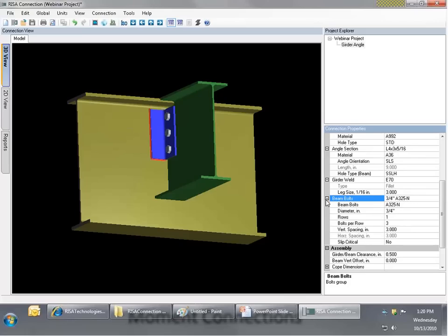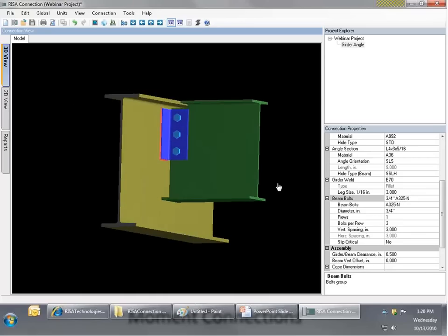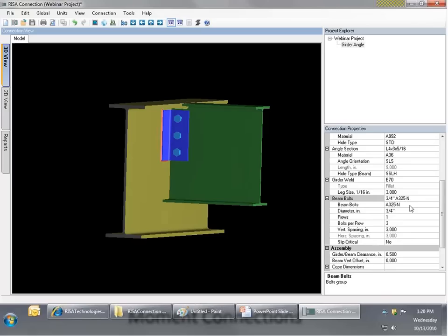And that's what's been set up here, but if I expand this out, you could see I could actually come in and I could set this in any number of different ways. For now though, let's say that I did have these beams with this 45 kip load. I know I want to do a single angle connection, but that's all I know so far. Well, that's really what the intention of the program is. It's that we set up the very basic geometry for this connection, and then we start making adjustments until we can actually get the entire connection to pass.